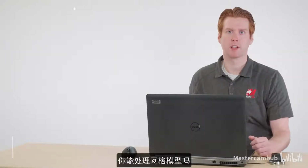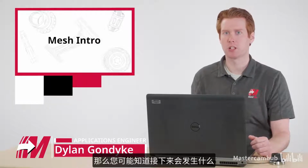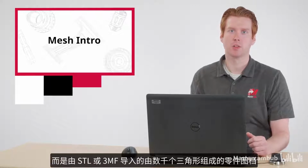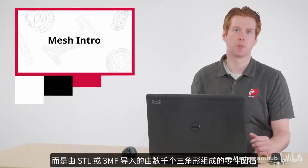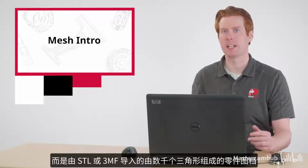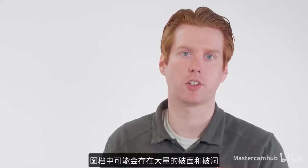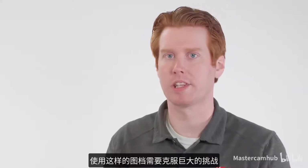Can you work with a mesh model? If you've heard this phrase before from a customer, you probably know what comes next. Instead of a clean NURBS solid, you'll be looking at a part comprised of thousands of triangles imported from a file type such as STL or 3MF, and data that might have numerous holes or other imperfections that immediately present challenges to overcome before you can work with it.